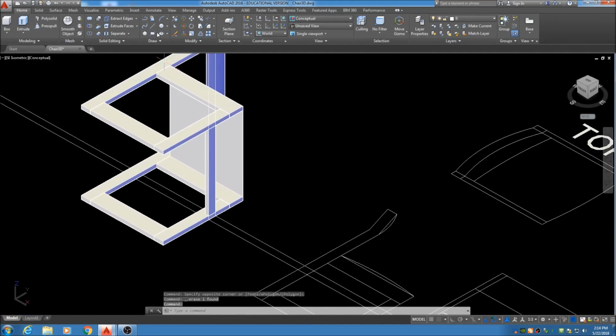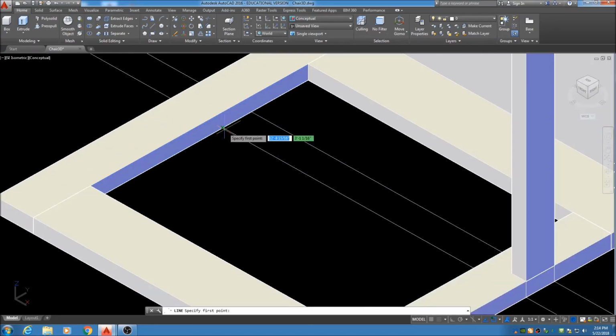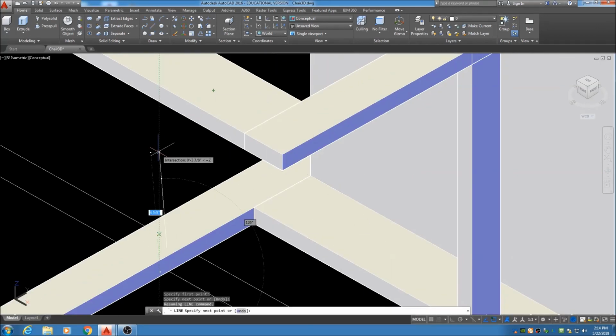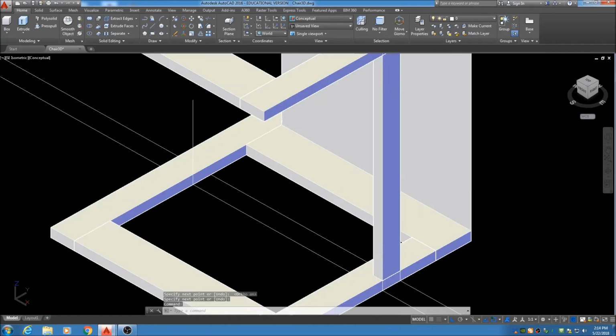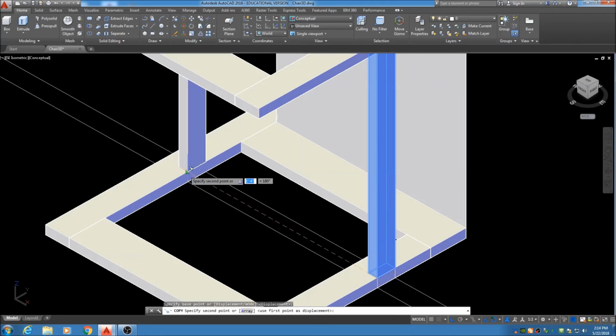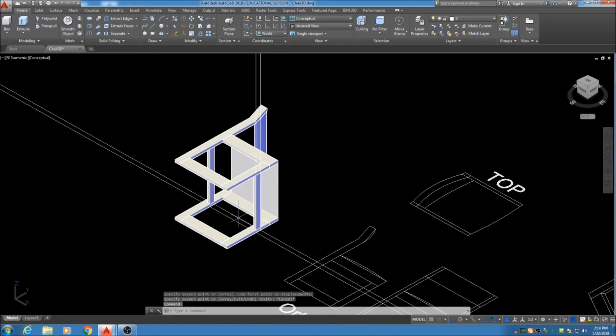Now, actually, let's do one back here. I'm using the regular line tool, and I've got the ortho turned on just so I could line up this, because I'm going to copy this and attach it to here because there's also a bar hidden in the back. All right, I think that's the full chair.